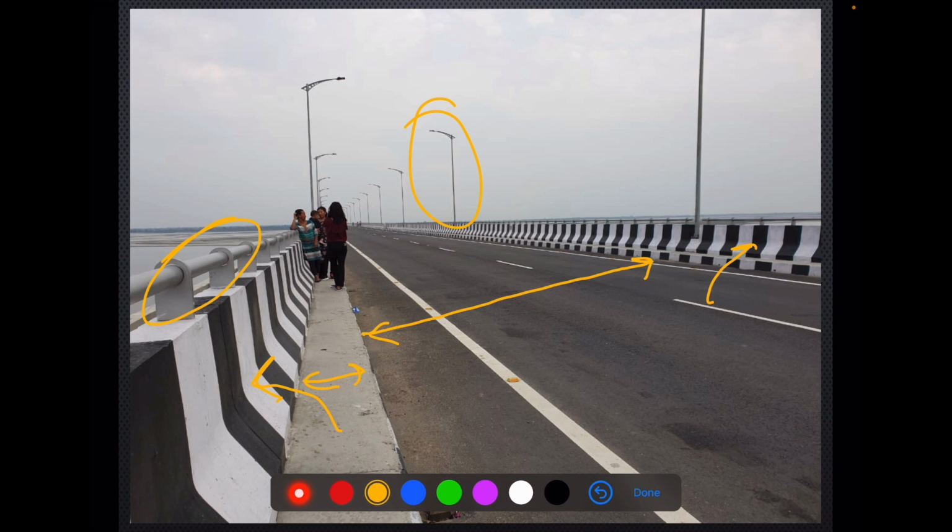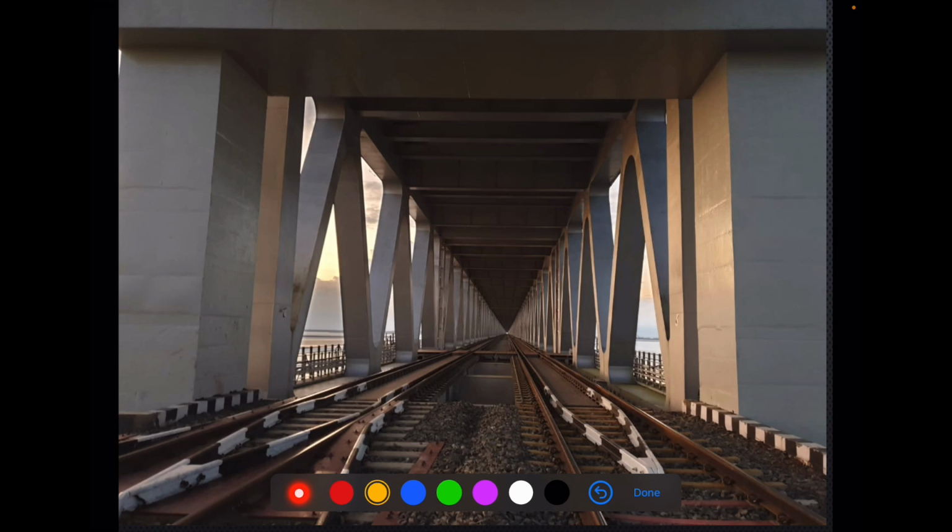And if we go to the lower level of the rail cum road bridge, it looks something like this. So there are two tracks, as you can see. Track 1, we may call it, and track 2, we may call it. Then you will easily see that these are the running rails for track 1, and these are the running rails for track 2. Now, these are the guard rails. These are the guard rails for track 1. These are the guard rails for track 2. What are guard rails? We have already explained in the previous chapters.